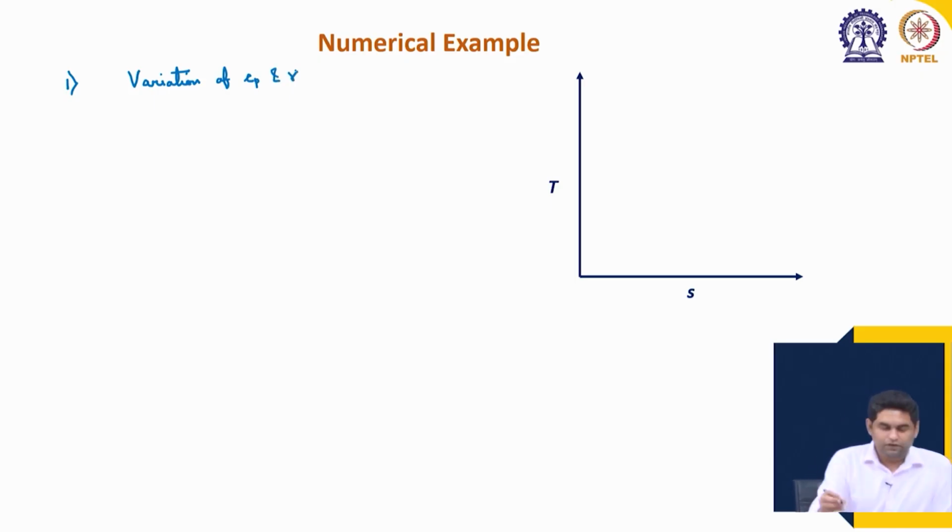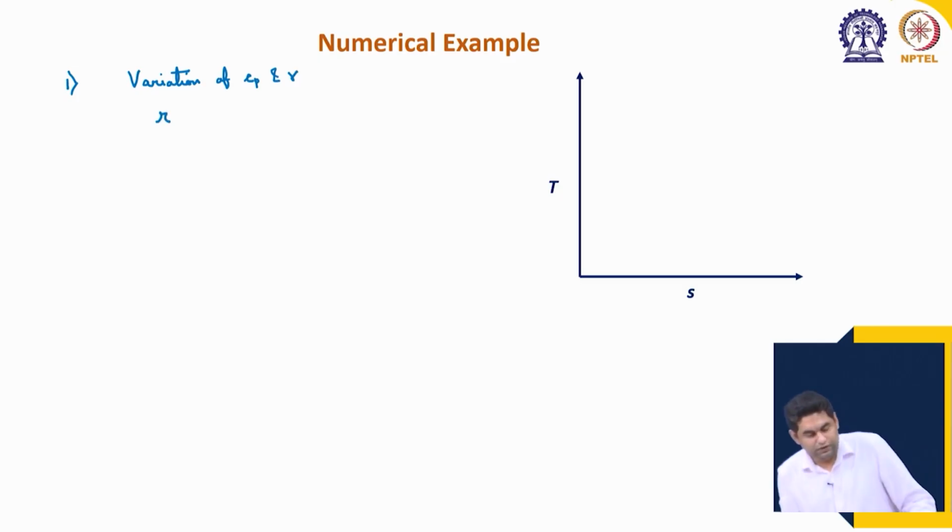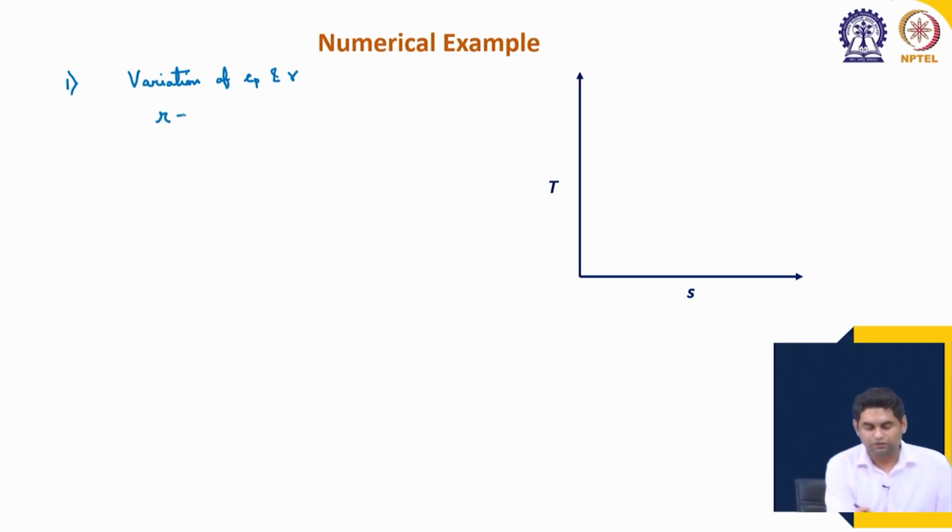So, we have a gas turbine with a compressor pressure ratio of 10 without any losses. Also the temperatures are given. Let us use stagnation values to make it more accurate. T01 is 300 Kelvin, T03, which is the Tmax value, the turbine inlet temperature, is 1500 Kelvin.